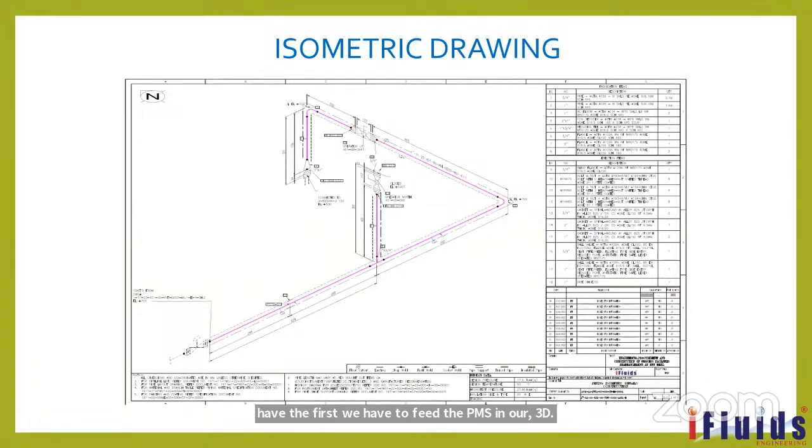That is a different thing. But while checking, before we issue to the contractor, there will be a revision table. Initially the first revision will go for internal review, the second revision will go for another one, and so on. Finally it will go as approved for construction or issued for construction, that will be AFC or IFC. Finally we'll go to the contractor side.